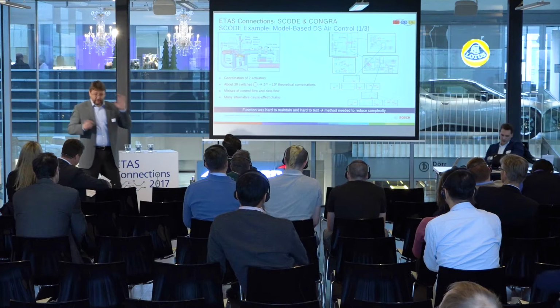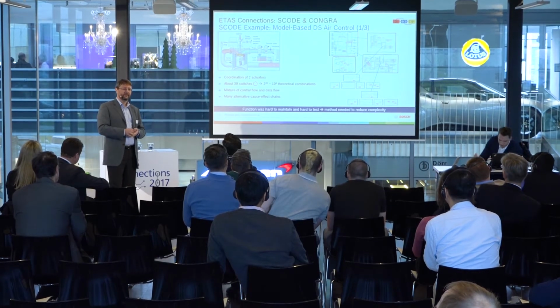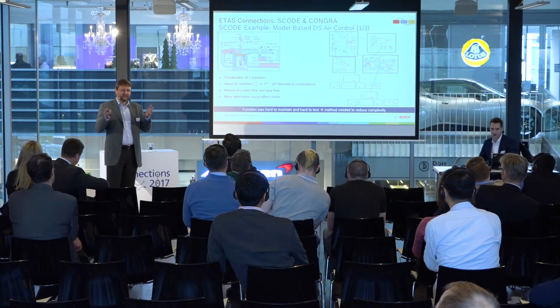We have lots of switches, and these switches are scattered. They're scattered everywhere because we will set switches only where we need them in a block diagram. They are local switches where I have to decide, do we go left-hand side or right-hand side? Min, max are switches. That's not continuous, it's a switch, especially when you go to the C code level. You will see that it is a switch. So 30 switches. So 2 to the power of 30 possibilities, that's 1 billion possibilities.